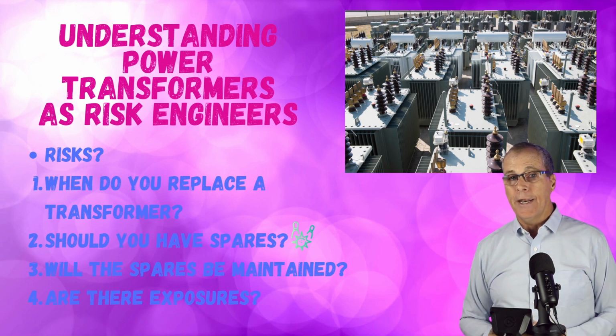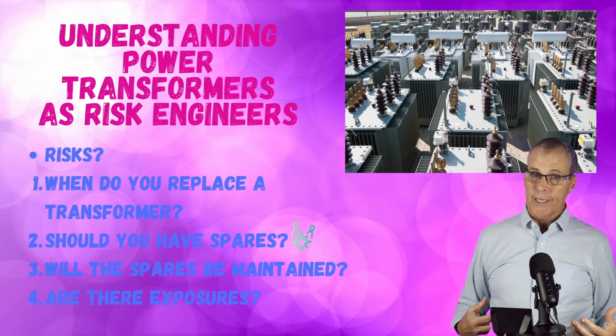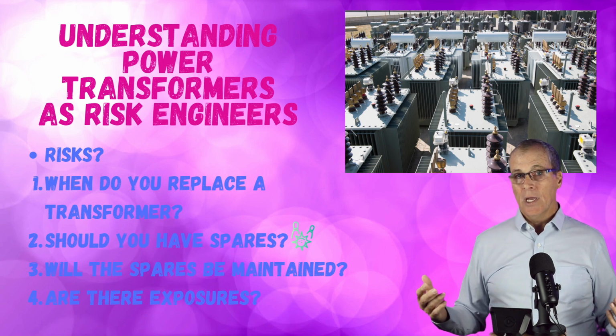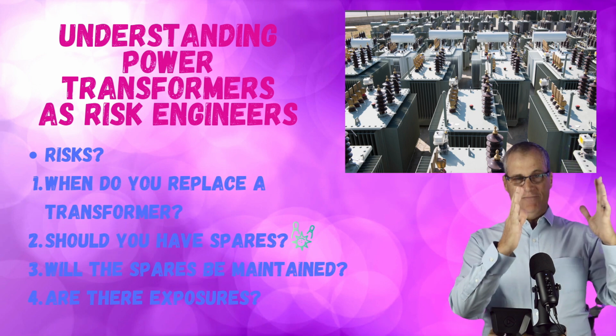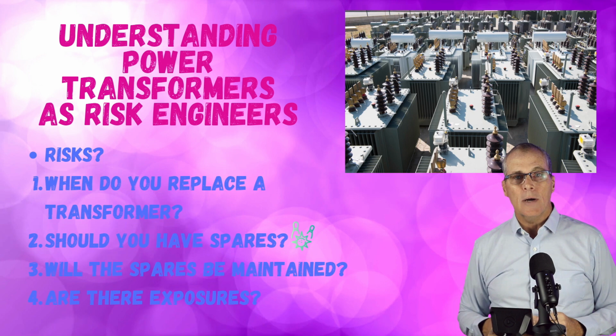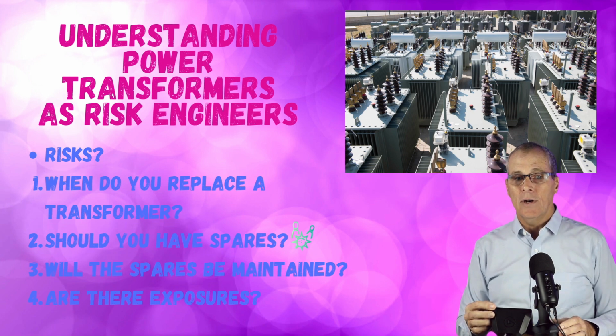Believe me, we've got it down to just $100,000. Believe it or not, we even have one way to get a firewall in there, say a 16 by 20 firewall in 4 pieces for $20,000. And it's made out of concrete, a foot thick at the bottom, 8 inches thick at the top. It'll stop a fire, and it'll stop a blast. So there are alternatives that don't have to cost $1 million.